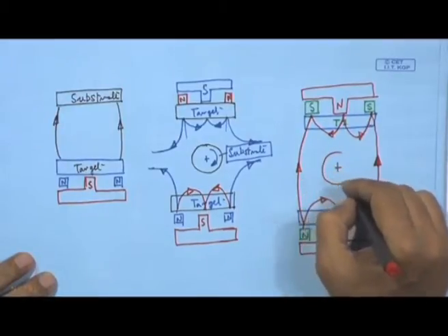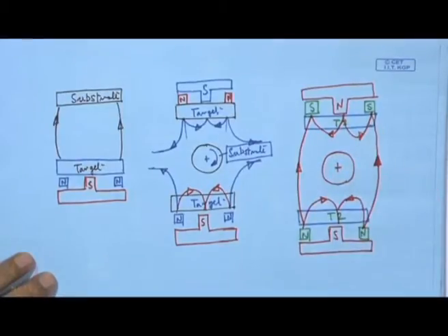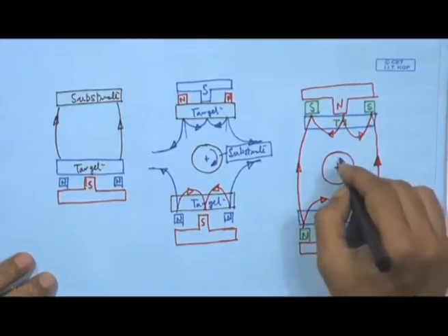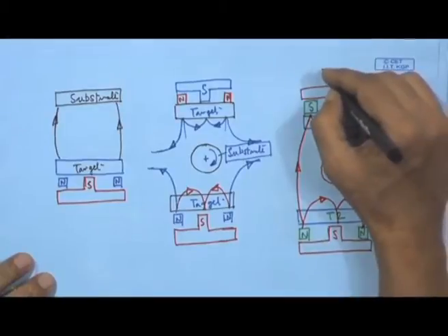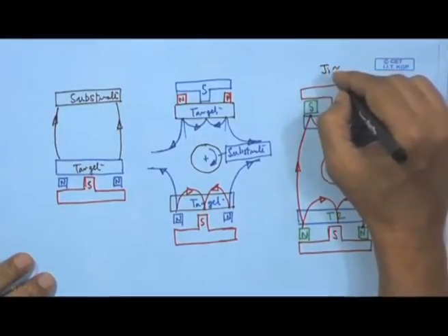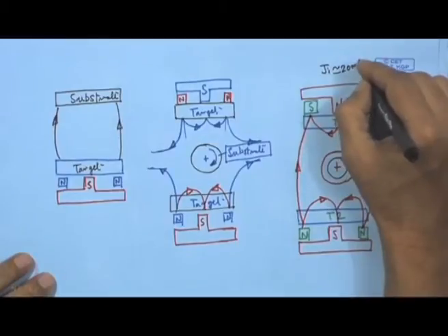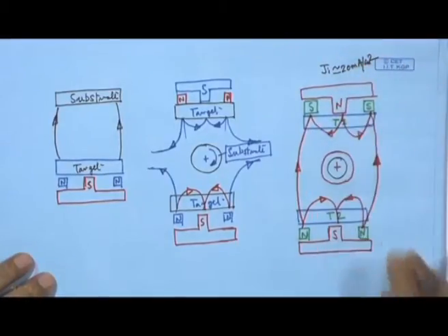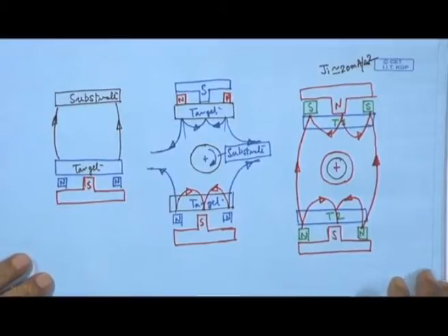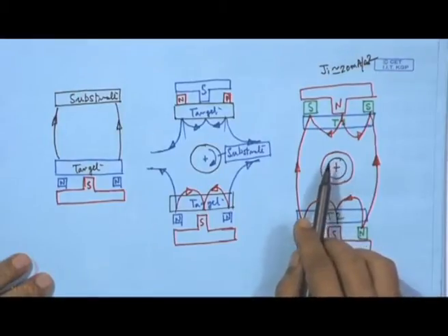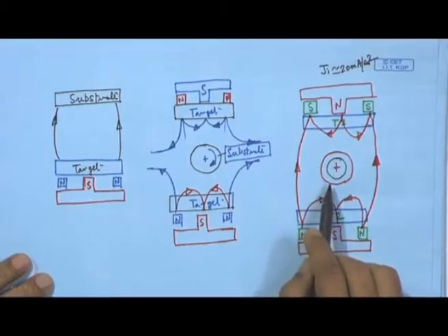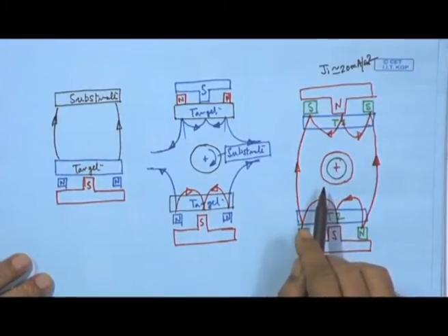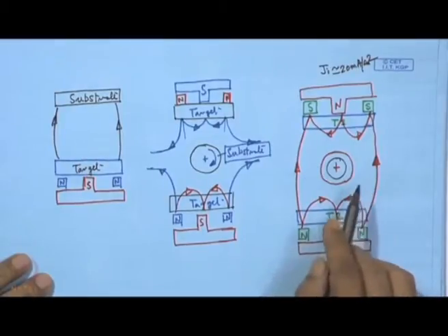And this whole area region becomes the plasma volume, and if one places the rotating table and the substrate over this, then it is submitted to very high plasma density, and this can be as high as Ji, as high as 20 milliampere per centimeter square. And to achieve this with this arrangement, it is not uncommon, and with this we can have a very high density coating, dense coating with all the required properties and uniformity of the properties.